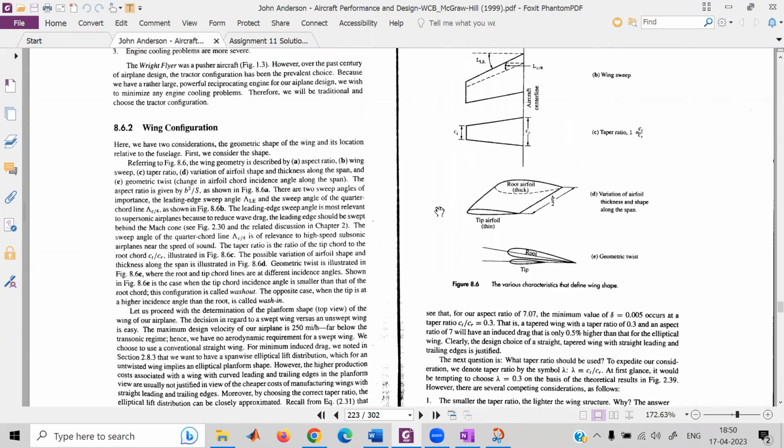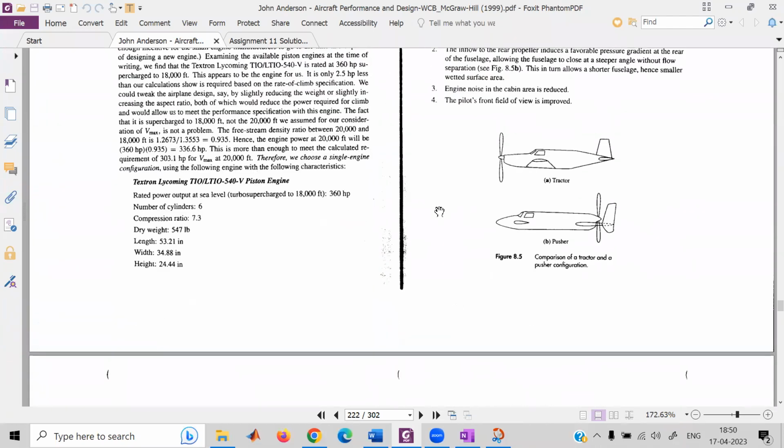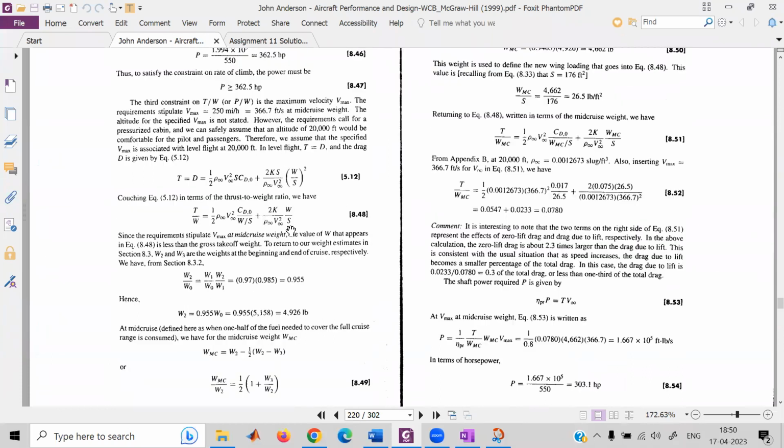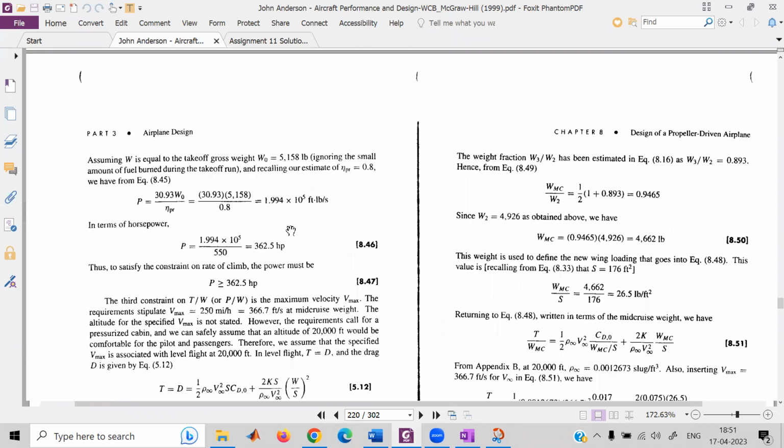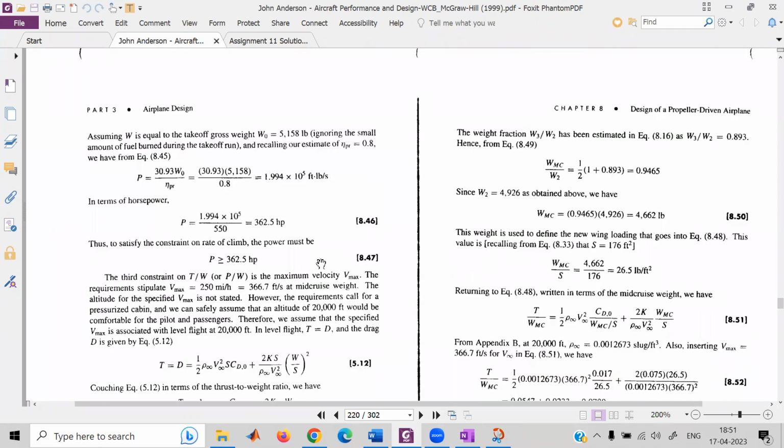And then we said that is for airfoil, then we convert it for the wing. Not by the formula, but by simply saying that we are taking 90% of what was valid for an airfoil. So that's a rough guess actually. Because the complexity of the flow is much larger, it's not just a 3D wing and a 2D airfoil. That can be done with some known expressions, but it was found that 90% of that airfoil CL is usually good.